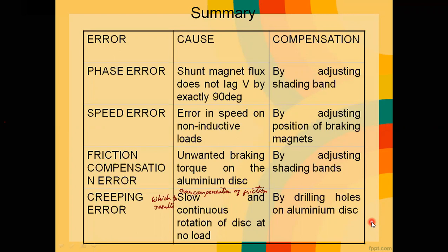What happens is we will have a distorted magnetic field, and hence you will not feel the overcompensation of the friction, because the field is distorted, so there won't be much movement of the disc at no load condition. So this is one cause. One cause is overcompensation of the friction. The other one is vibration, as we have seen in detail in the earlier slides.